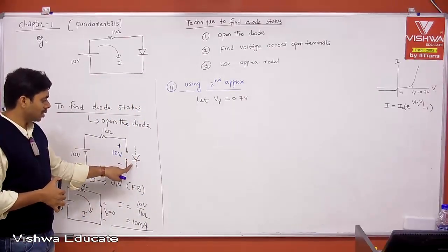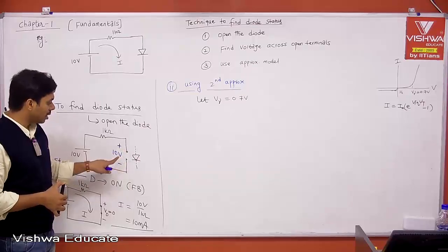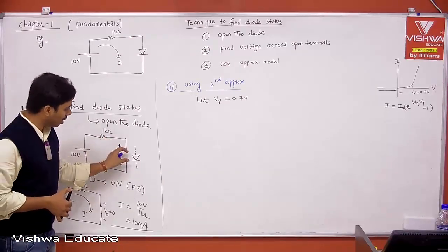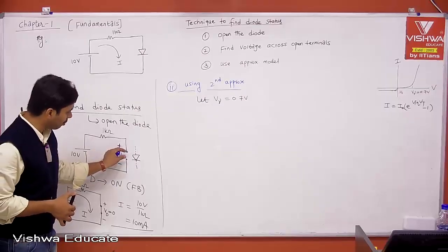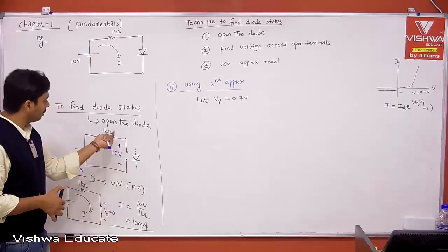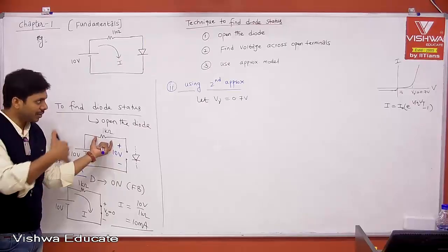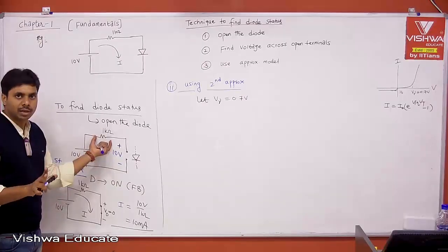The voltage across the PN junction diode before connecting the diode is greater than or equal to 0.7. Yes. Then it takes only 0.7 out of 10 volts. The remaining 9.3 will be given to the 1 kilo ohm resistor. I'm just explaining qualitatively, but if you do the math, you get the same thing.